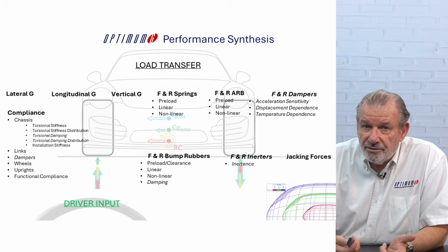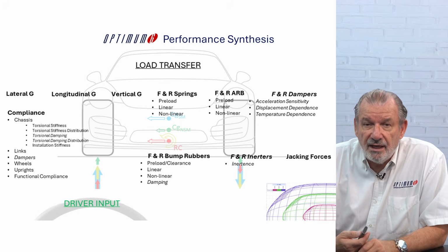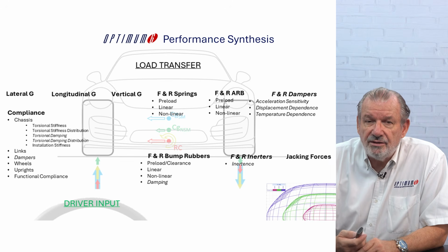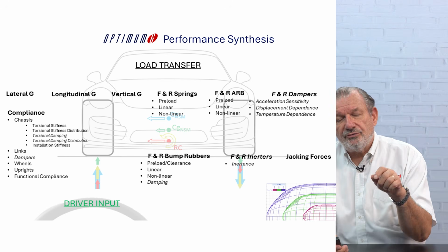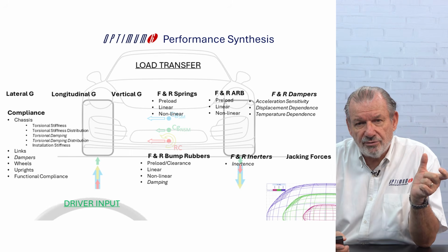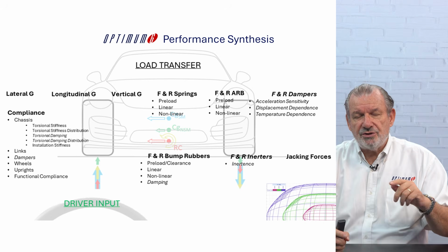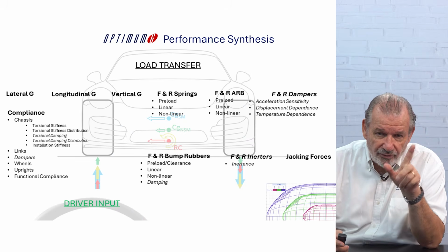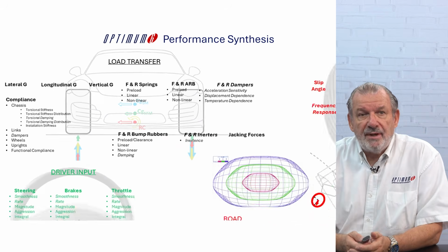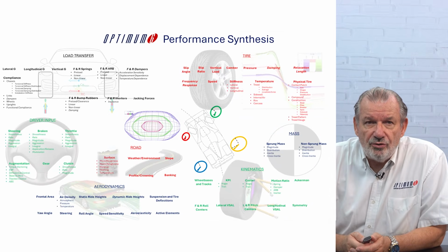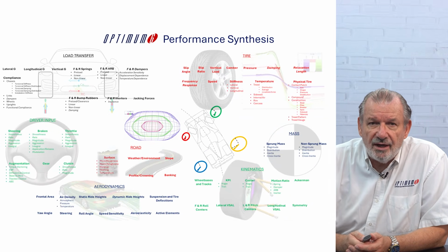The front and rear inerter, which are helping you to control the acceleration, and then the jacking force, understanding the jacking force, how much, because of the distribution of the lateral grip on the inside and the outside wheel and the position of the instant center, you can create different jacking force, which means, by the way, that you are not at the right height you think you are, and therefore you are not in the same cell of your aerodynamic map.